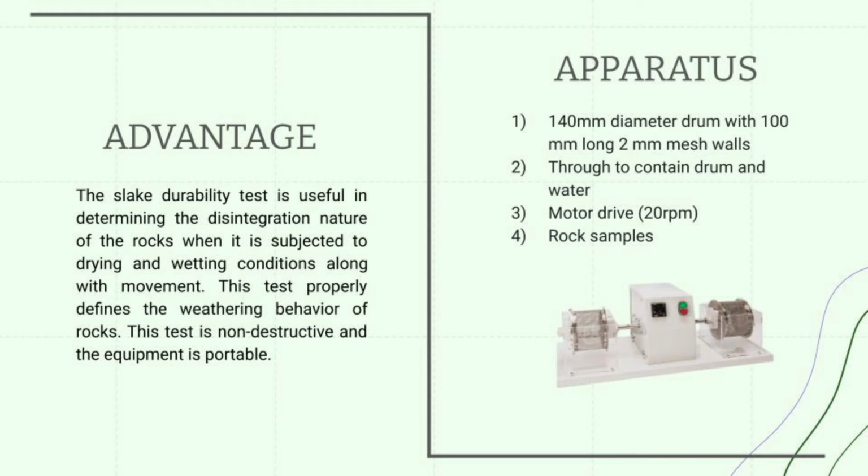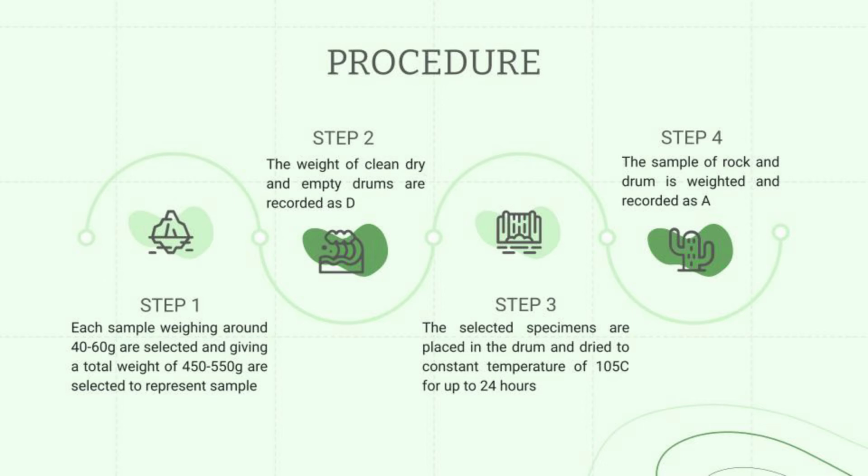The apparatus that we need for this test is a 140mm diameter drum with 100mm long 2mm mesh walls, a trough to contain the drum and water, a motor drive which is 20 rpm, and rock samples. Next we proceed to the procedure.